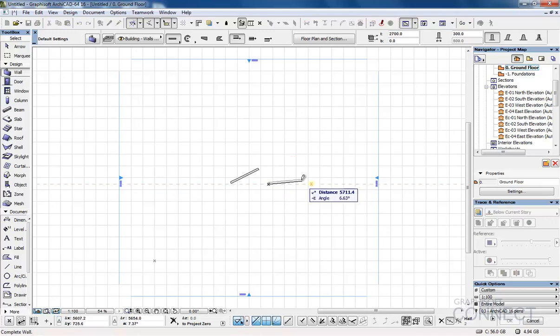If I do another one, again, a couple of other things happening. First off, I suppose, is these orange guidelines, and these allow me to snap to the x-axis, to the y-axis, or even to 45-degree increments, and they're all labelled up so you know exactly where they are. So if I just wanted a random wall on the x-axis, I can snap the mouse onto here, give the mouse a click, and I know that that wall's exactly straight.